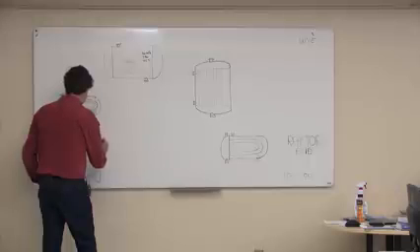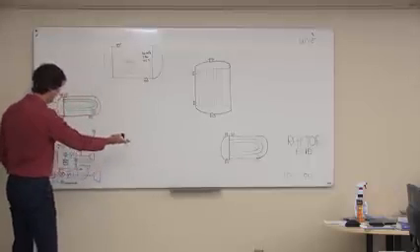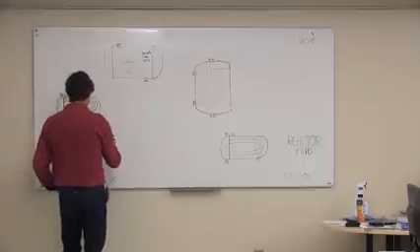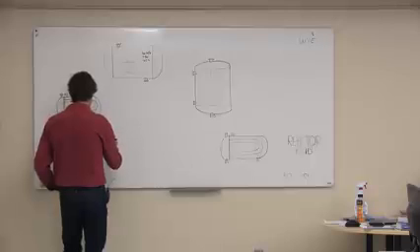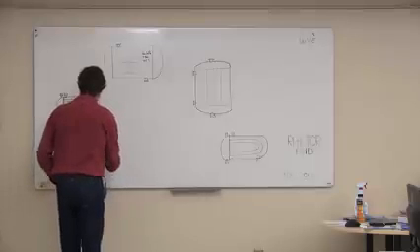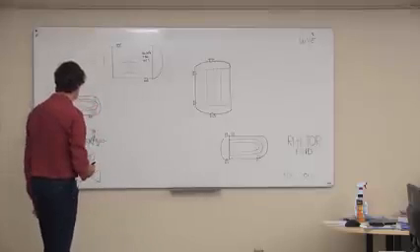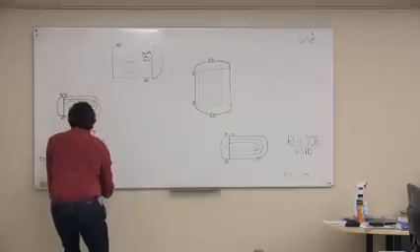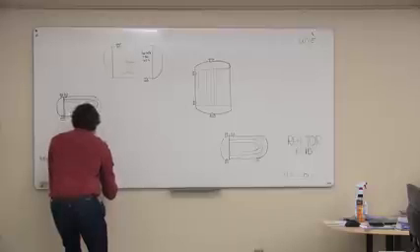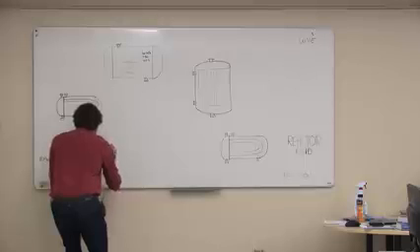And then generally you want to put a check valve in. So the check valve prevents liquid, or water in this case, from flowing backwards through the pump. That's particularly useful when you want to start the pump up. And then we need to put another block valve in. So it's another manual valve. And then we can join the pumps together. So then we're just basically going to duplicate that. We'll come back and do the controls on the steam turbine later, because they can be a little complicated. Like that.